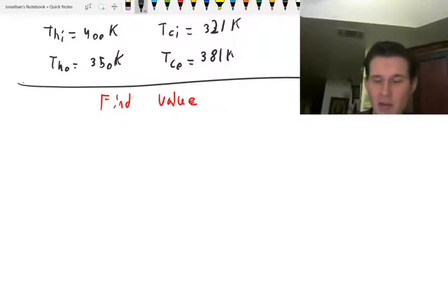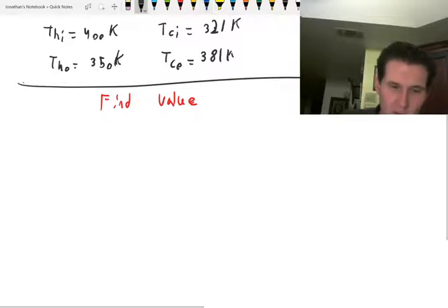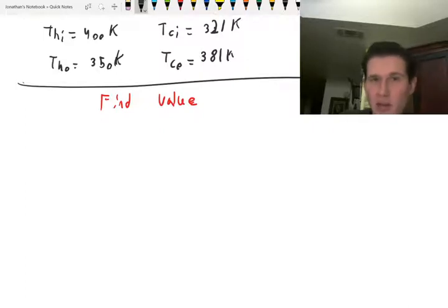How do I take my values? Well, I'm glad you asked. We have our T hot coming out, our T hot coming in. The values at the place where it's coming in hot are only applicable at the beginning. How about going out? Only applicable at the end. In between there, those values are going to change. Your viscosity is going to change. Your CP is going to change. And it's not going to be constant.